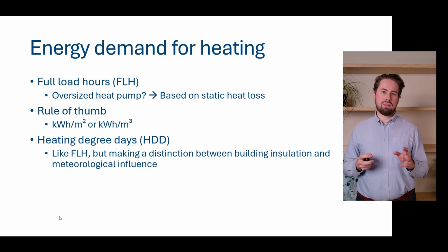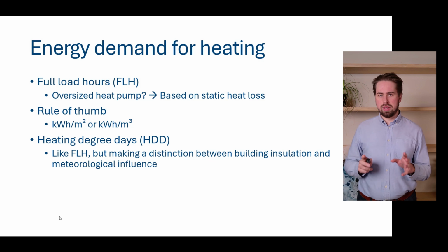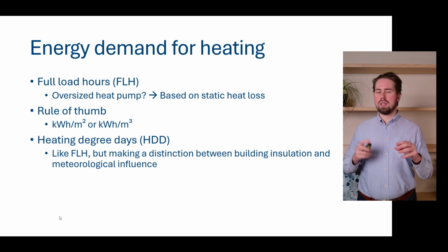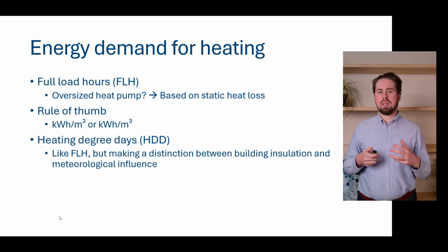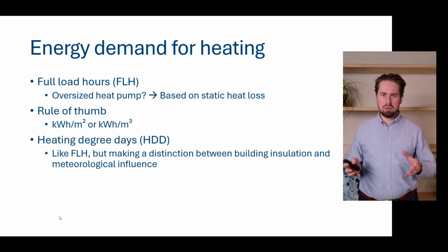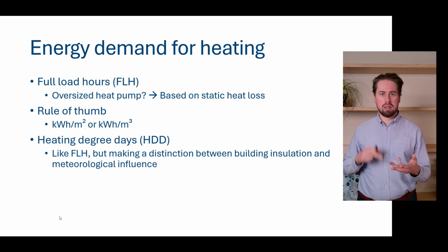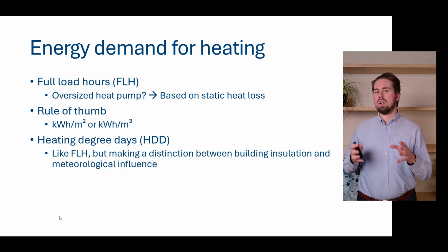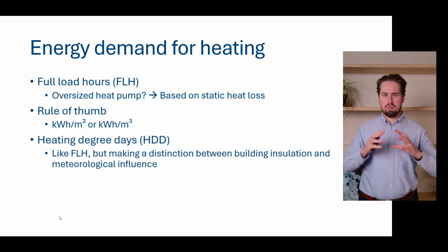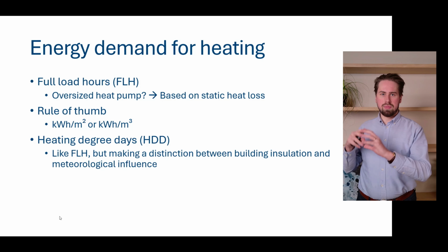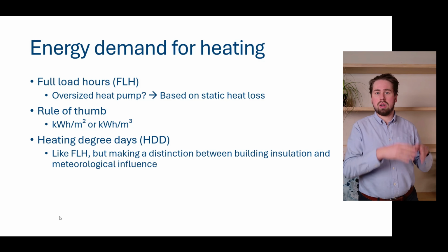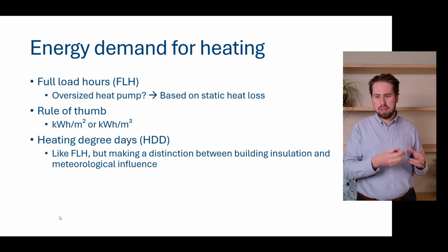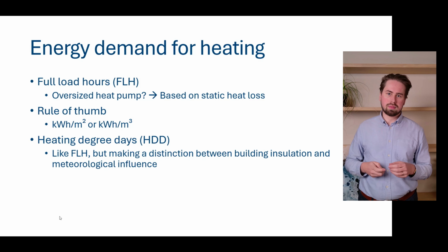There are also rules of thumb, kilowatt hours per square meter or kilowatt hours per cubic meter, you can use. And you also have something called the heating degree day method. Now, this is a little bit like the full load hours, but instead of having just one value encompassing everything from climate to building insulation, usage, etc., we're going to make a distinction between building parameters, insulation and so forth, and environmental parameters, or climate, let's say, or weather in a specific region.